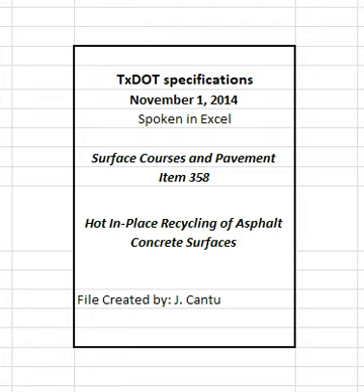Ensure the temperature of the milled surface directly behind the milling heads is greater than 160 degrees Fahrenheit so cold milling does not occur. Clean all loosened asphalt material away by the milling heads, and a milling tooth pattern must be clearly visible after milling. Remove all material around manholes and utility structures before paving the recycled mixture to allow for the planned depth of the pavement around these structures. Cold mill and sweep clean any areas that cannot be heated and milled by the recycling equipment. Properly tack and pave these areas of cold milling in advance of the recycling process.